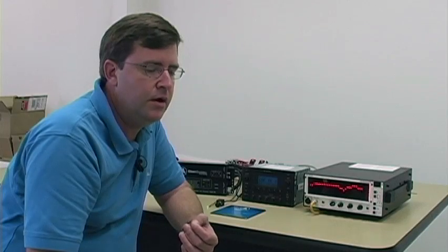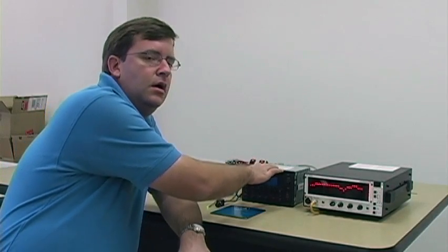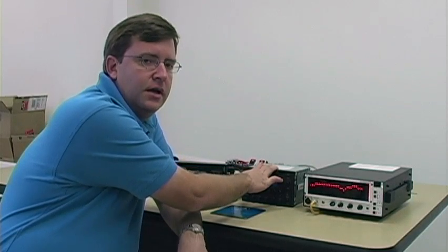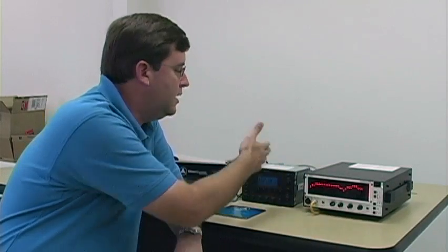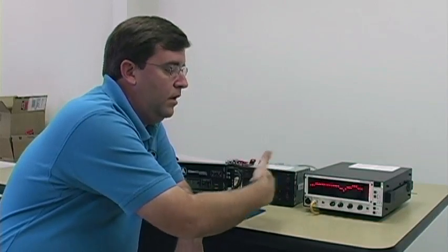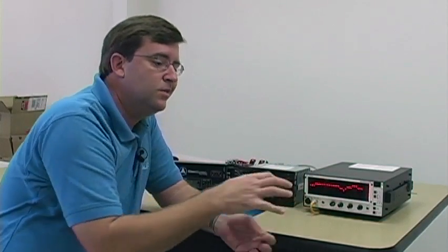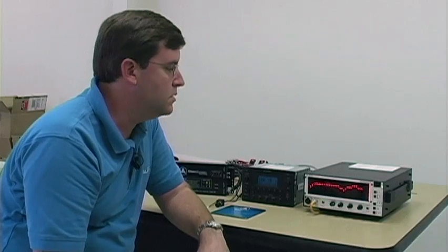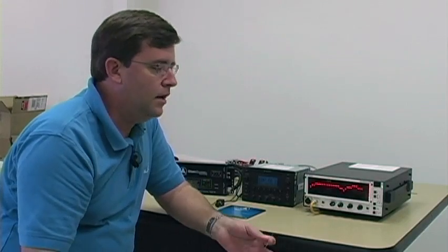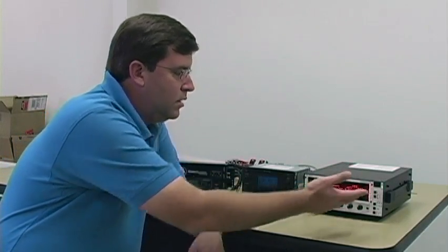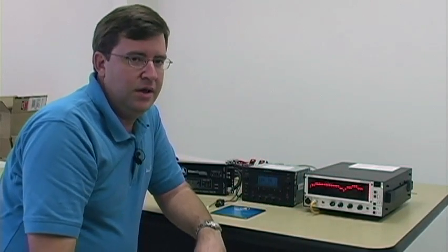The factory systems apply this equalization almost always now. It's become very cost effective to employ a small DSP processor inside these head units, and they have some free horsepower left over to apply these kind of corrections. So they take advantage of that, because they want to give their customer a better listening experience with the limited resources they have in terms of the speaker quality they use and the locations that they choose and all that good stuff. The problem is when we put in a really nice pair of speakers in the car and a nice subwoofer, we're dealing with a curve that fundamentally starts from a bad place.